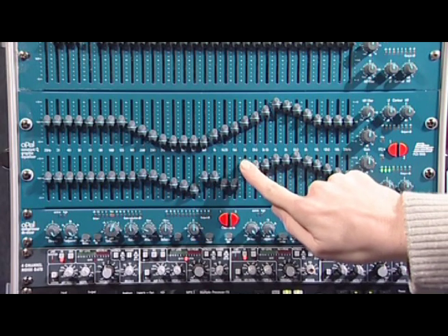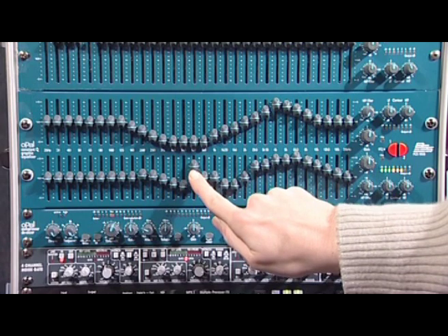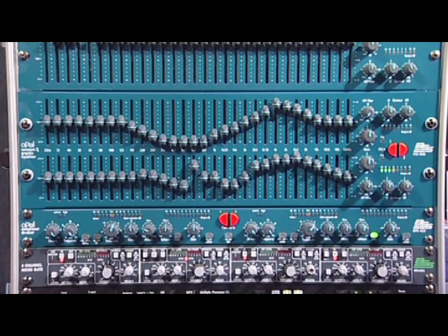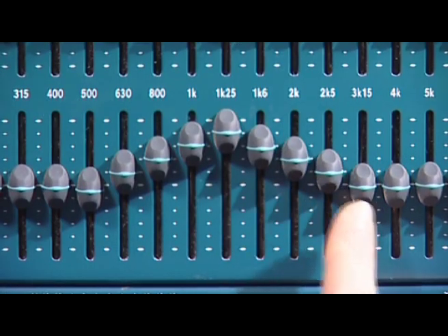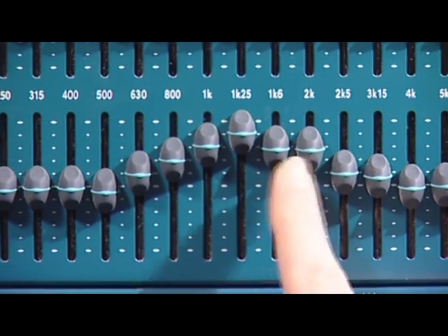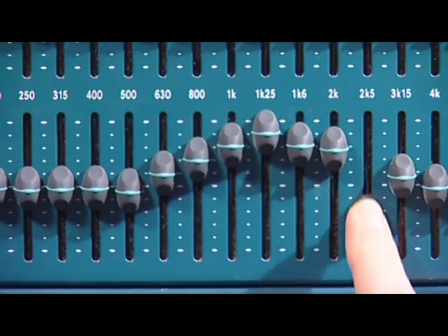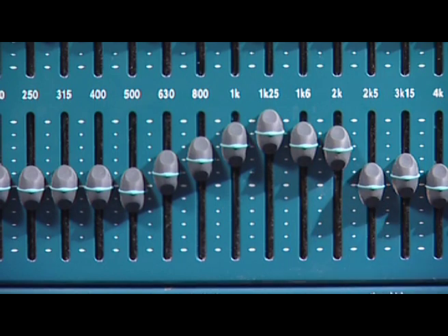Graphic equalizers can cut or boost a large number of fixed frequency bands. They're called graphic equalizers because you can see the shape of the EQ curve from the position of the controls. Even though the frequency bands are fixed, there are enough of them for you to be able to focus fairly precisely on one or more problematic frequency. They're especially useful for isolating and notching out feedback frequency hotspots, and for generally improving the sound of a live venue.